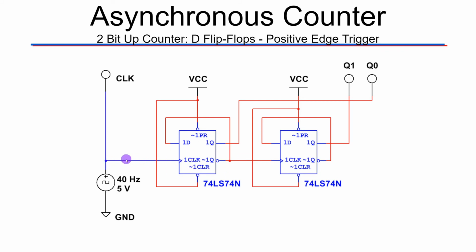So our frequency going here is 40 hertz, or 40 times a second. That means the signal on this line is going to simulate a clock signal that's actually only 20 hertz, or 20 times per second. And that halving is going to continue every flip-flop because it takes 2 edges to actually change that behavior.